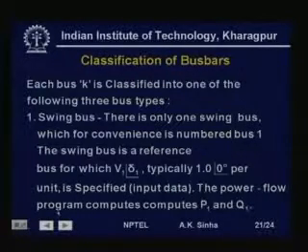The power flow program computes P1 and Q1 for this bus, that is the unknowns for this bus will be P1 and Q1, that is injections at this bus, because we have not specified the generation at this bus. So, we need to calculate that finally after we have calculated the voltage at all the bus bars.